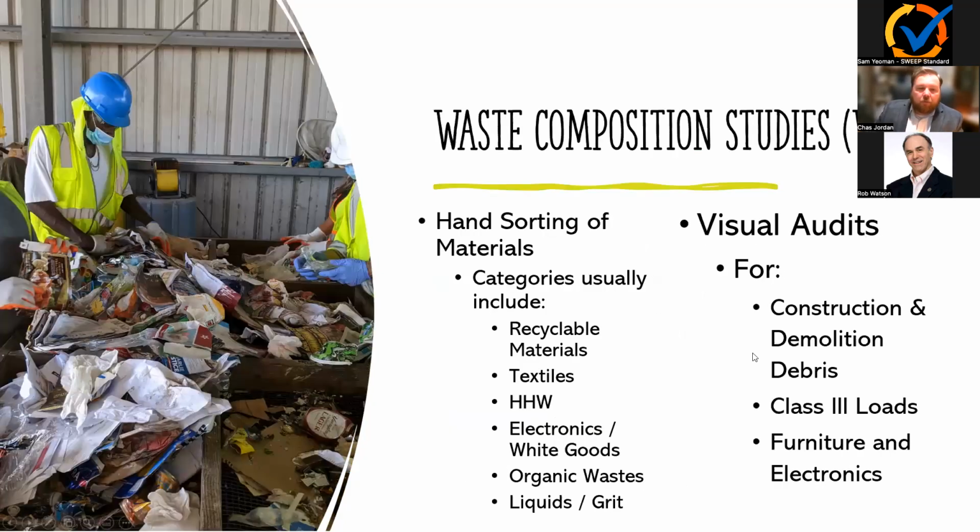So the one that probably everyone on this call is most familiar with is a waste composition study. Waste composition studies are studies done of inbound solid waste, which is usually termed class 1 or a municipal solid waste or whatever your term may be in your organization. But these studies review the total tonnage of material collected by an agency over the course of, we aim for at least 12 months. And then over the course of 1 to 2 weeks, we pull samples collected from across that stream's input sectors and then sort it.